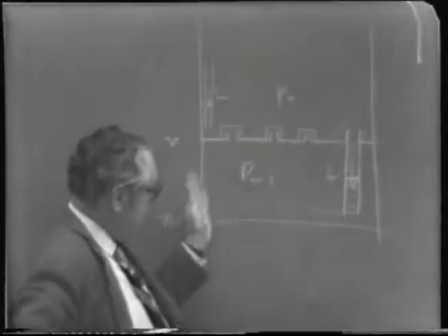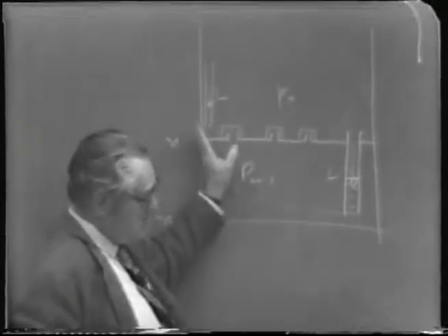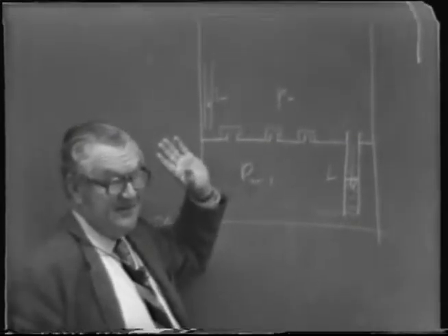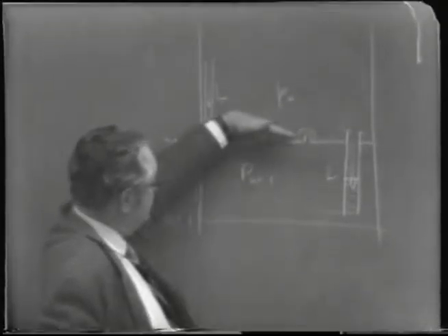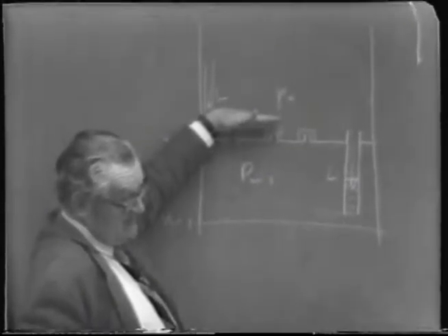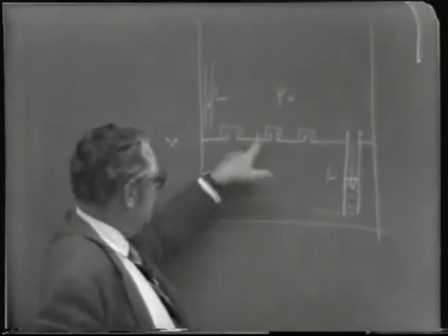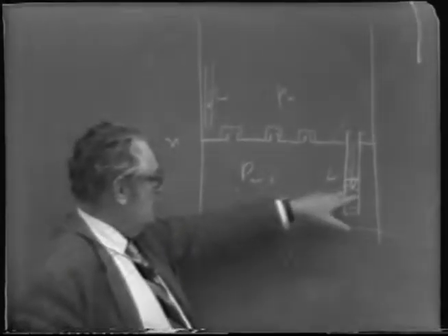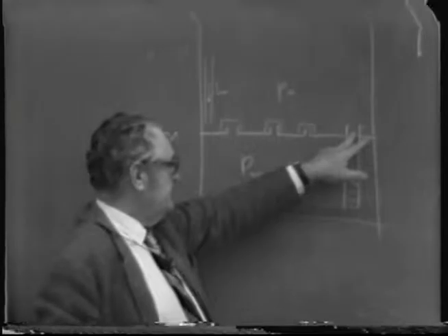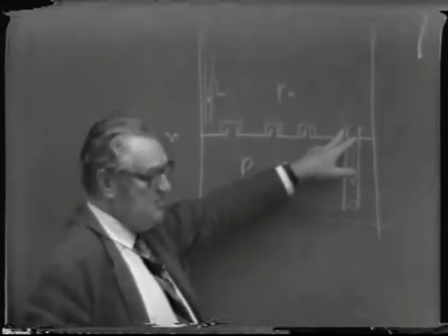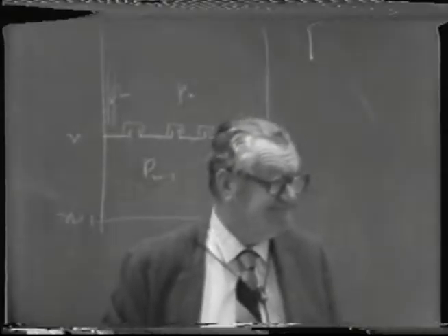But obviously, any factors that increase the pressure drop across the tray, such as a greater vapor velocity, greater loading, greater flow here, you have a higher liquid level, and you have greater hydrostatic pressure drop of the vapor passing through the liquid, as well as the friction through the openings. Increasing pressure will eventually cause this liquid level to build up here till it's equal to the level on the tray above. And when you have that situation, you have flooding or priming.